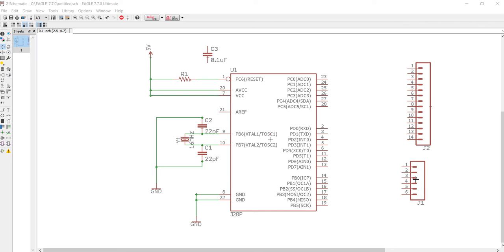So we're actually going to take power from this, and I've gone ahead and looked up the pin out ahead of time. The first pin here is going to be a ground line, so we're going to do the same thing, copy our ground and connect that right there. Yep. The next line is going to be CTS.